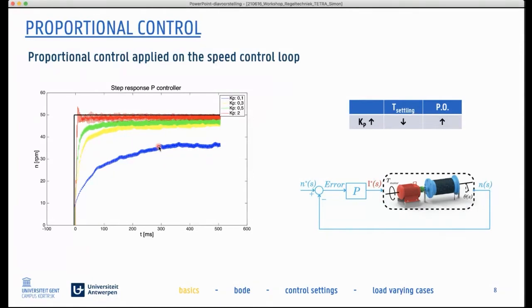You want to go to that speed quite faster, and you increase the gain to 0.3, for instance. You see that our controller is already reacting much faster, and that's normal because a smaller error in rotations per minute results in a larger value for the current, so a larger input of power, and we will go to that desired position quicker.